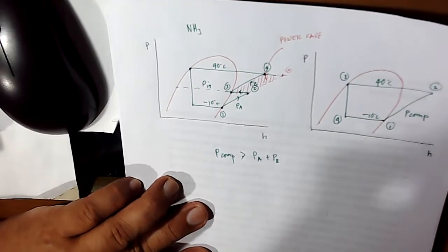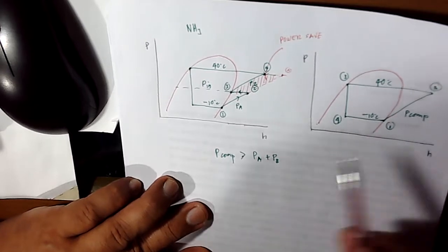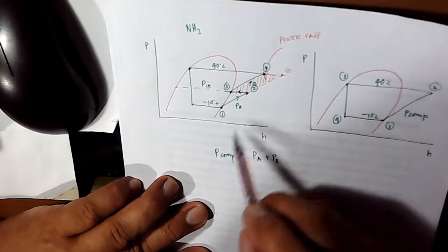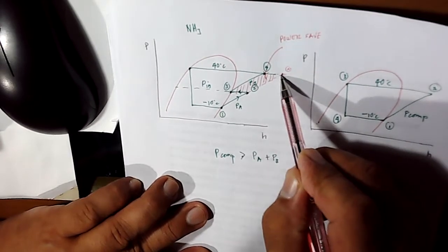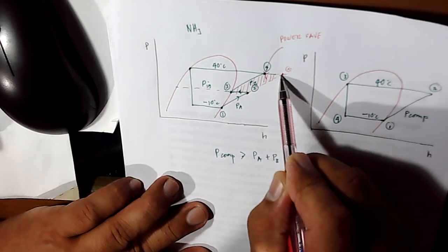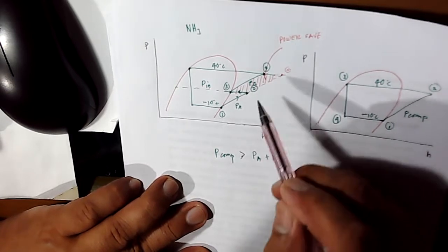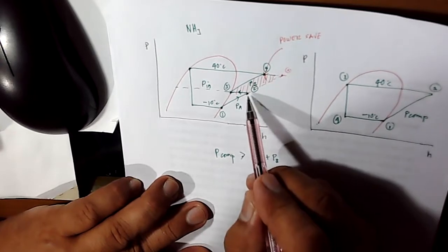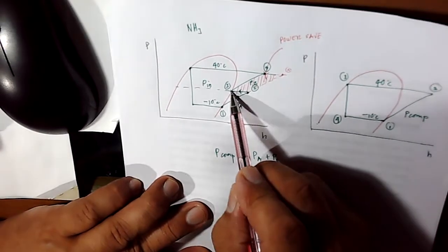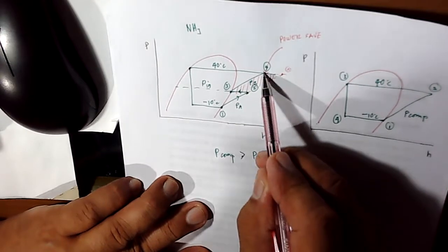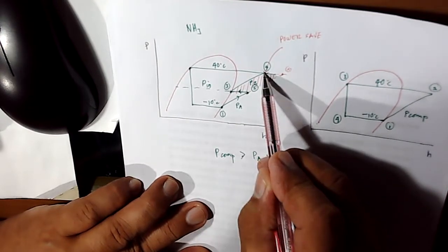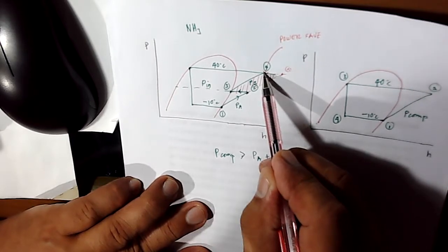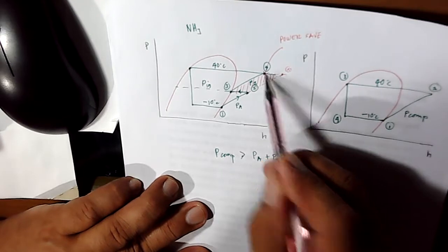Yes, power save. Again, if you are going to use only one big compressor, then we have a straight line going there until it crosses the pressure corresponding to 40. However, by using an intercooler, we have two small capacity compressors that convert point 2 into saturated vapor before entering the second stage compressor, the higher stage compressor, for a complete compression of the refrigerant in the system.